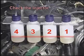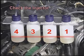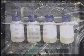From the results of the back leak test, the amount from the number 3 injector is higher or lower than the other injector. With this information, you would assume that the number 3 injector is defective. To verify, you should check the results from the high scan test.